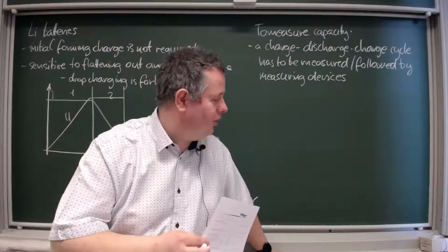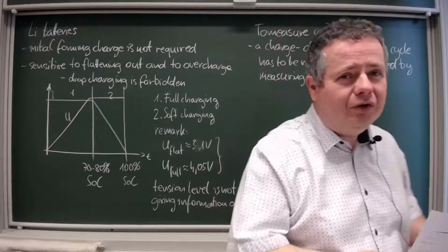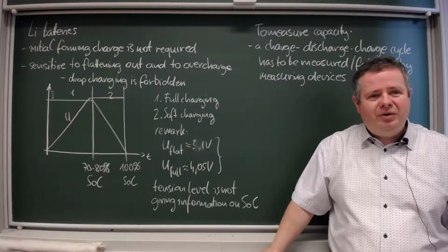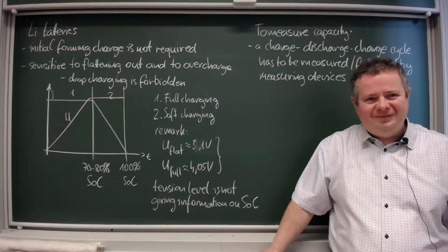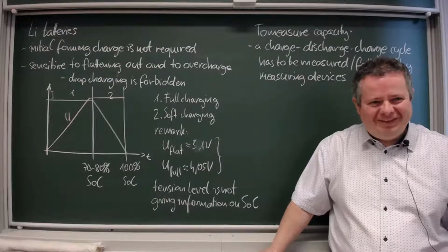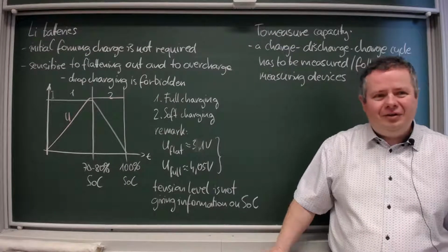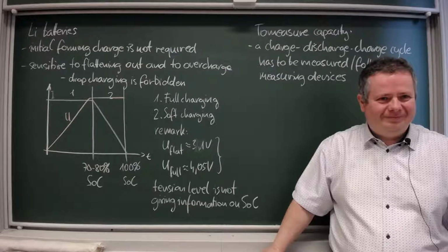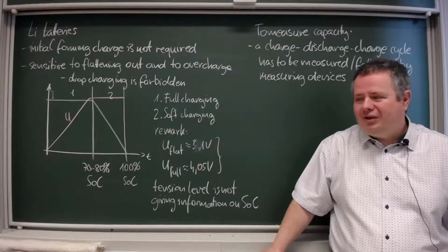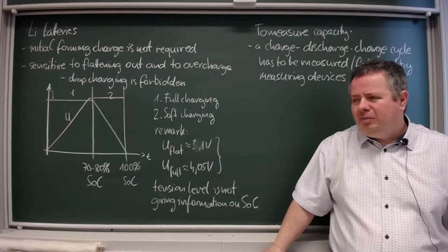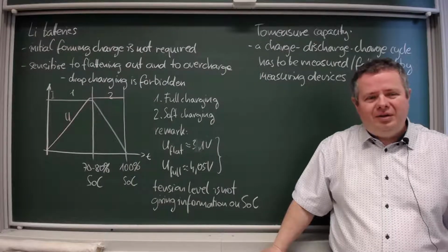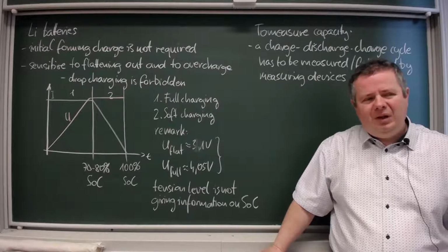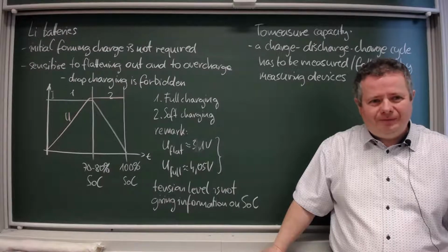And how can they discharge a battery? You've got large batteries, let's say half a ton of weight. The discharge is as simple as possible. For example, you take the internal heating of the car, and you set it to the maximum. So the heating ventilator is going at full charge, and you wait some hours. So it's easy like that. Unfortunately, it takes time. I have no information about how Tesla is doing that, but I'm sure they've got something similar. But as they are more developed on the software side, maybe they are just checking by charging.